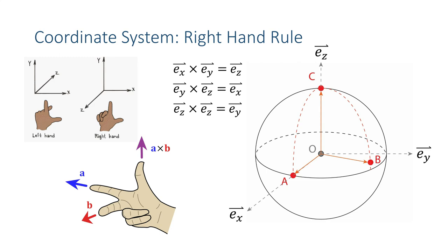If you were putting a screw in a wall and you were looking at the head of the screw, standing back, and you twist your screwdriver, say you put a force on B, so it rotates your screwdriver around the Z axis, that means you're going to have a positive moment that is putting that screw into the wall. It's going in the positive Z direction because you're putting a rotation on it by applying a force to the end of B. Hopefully that makes sense. You're rotating it around your thumb, which would be the Z axis, and you're rotating it in, so that's a positive.